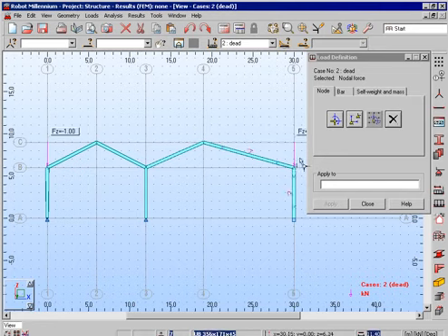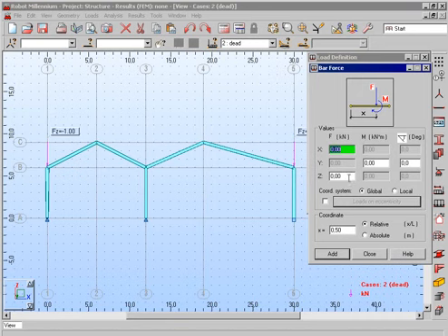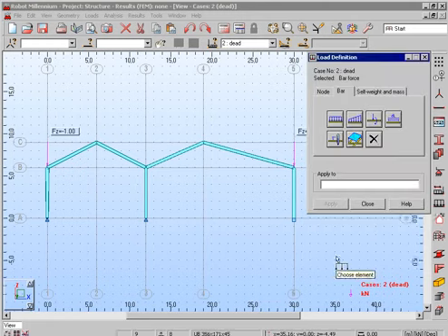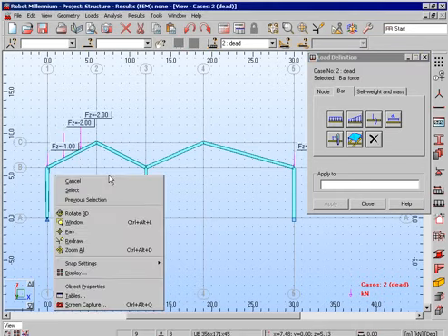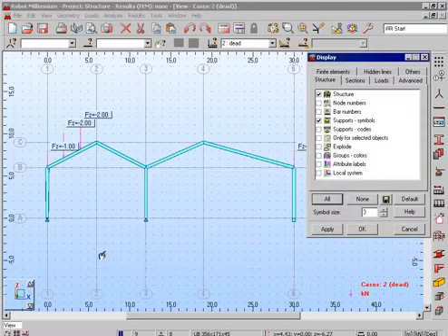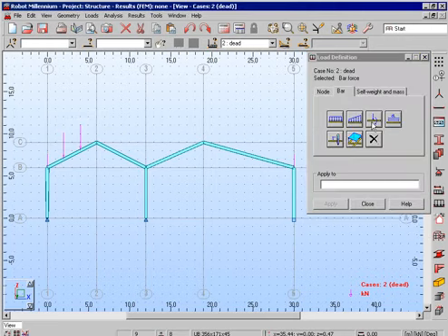And now we're adding on some simple point loads into the dead load case. And of course some member loads along the member. In this case 1/3 of the way along each member. Note in Robot how it's only necessary to indicate the end of the member that you wish to consider as the origin, and the program will take care of everything else.